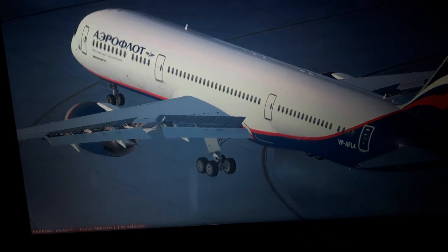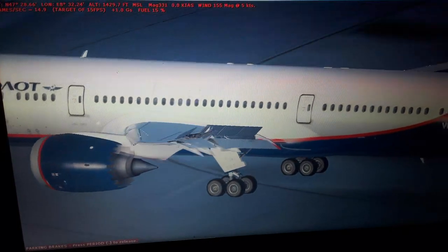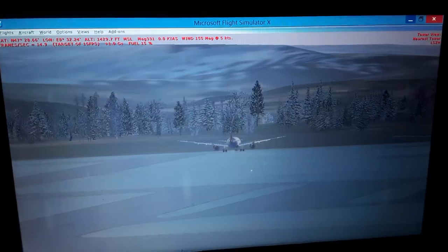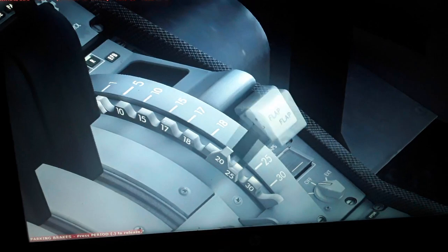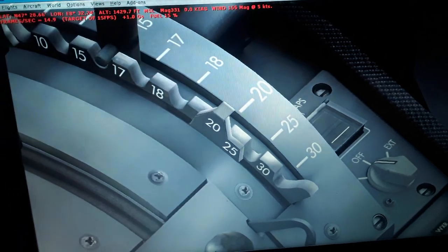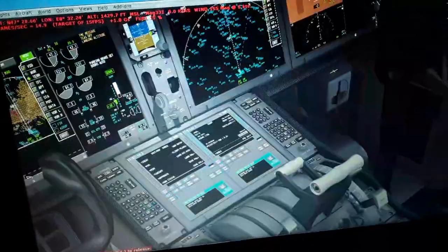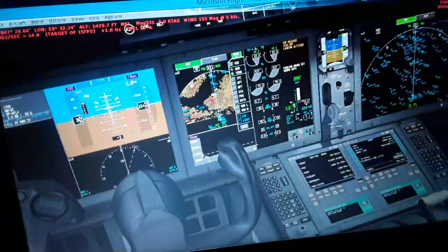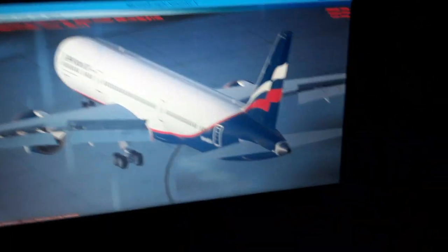So you will see also the outside view. The flaps now are moving down. You can fully extend them. So you can fully extend how many degrees you wish them to be. 18, 20, 25, 30. So you use the maximum for landing. You use like 5, 10, 15 for takeoff. Or less. So you see it keeps extending. Both sides are fully extended now.